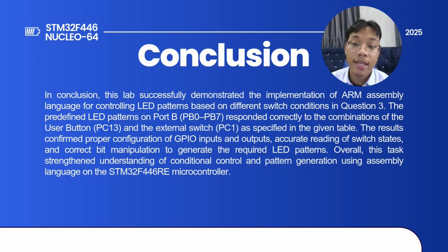For the conclusion, this lab successfully demonstrated the implementation of ARM assembly language for controlling LED patterns based on different switch conditions in question 3. The predefined LED patterns on port B, which is PB0 to PB7, responded correctly to the combination of the user button, which is PC13, and the external switch, which is PC1, as specified in the given table.